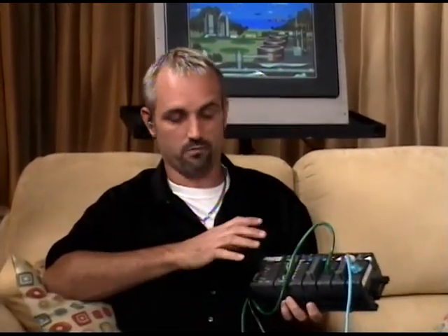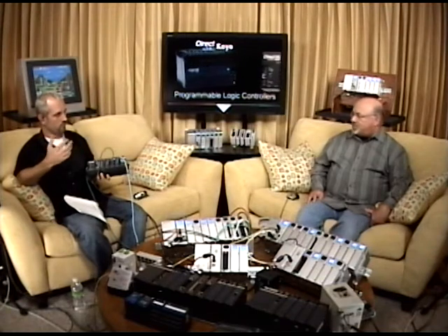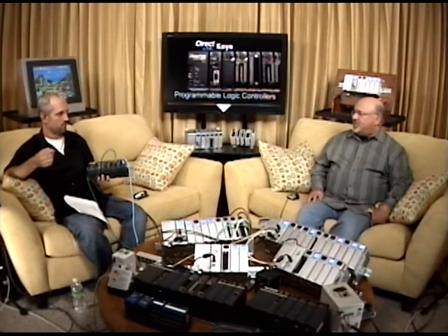Okay, all right. Some of the stuff we're mentioning, we say ERMs, EBCs, a lot of customers might not know what it is. But for remote I/O, if you're not familiar with Koyo or Direct Logic or Automation Direct, which is all the same stuff, our remote I/O used to work like this: let's say you had a 205 rack, which is one of these nice racks here, and I'll try not to get myself shocked. The 205 rack is one of the most popular. We've been selling these for years. But when you ran out of space in the 205, the only way you could get more rack was to use serial remote I/O. Now, we have a solution for that on the newer stuff. You can actually do expansion racks. But serial remote would allow you to run long distances, and like I said, it was a 2-wire with a ground, twisted shielded cable.